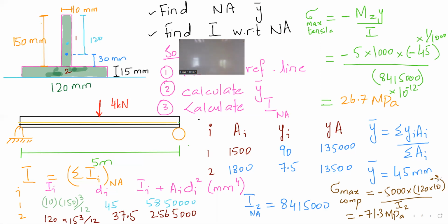For a rectangular section, it is not difficult. Rectangle is like this, right? So if the height is 20 millimeters, you go 10 above, 10 bottom. If you're talking about a circular section with a diameter of 20 millimeters, and I want to talk about maximum compressive or tensile stress, how do you figure? 20 millimeters is the diameter, so 10, 10, easy. This one is complicated because the structure is complicated. The object will have a centroid which you have to find by hand. And then how are we getting this moment at 5 times 1?